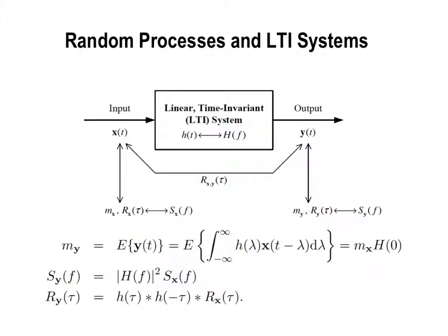Think about it this way: when I take the autocorrelation, okay? And for example, I find that my autocorrelation looks like this. Let's say I calculate this autocorrelation and I find that it looks, for example, like this. Right? What does this represent? Most of the values are going to come around some... not the value. Don't forget that the autocorrelation is the relation of the expected value of the current and some shifted version of the random process, right? And our x-axis here is going to be what? Tau, the shift, right? While my y-axis is going to be the autocorrelation value, Rx, right?